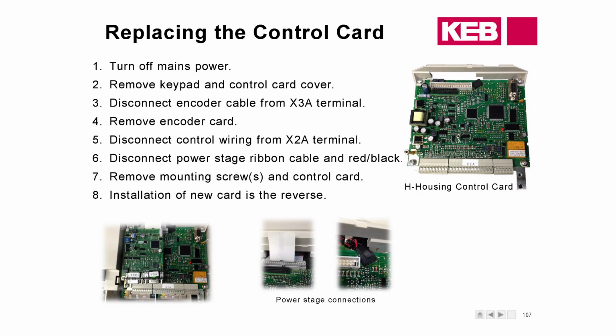Anytime you're going to make a control card change, we recommend you call KEB just to be sure that there are no software or hardware compatibility issues. With our most recent drives, within the last few years, it's fine. You can make changes, but it's around that 7 to 10 year mark where some hardware and software changes were made, and you might have a compatibility issue. Hardware-wise, specifically this guy here. So call us. We'll verify what you have and get you the right control card if you need it.